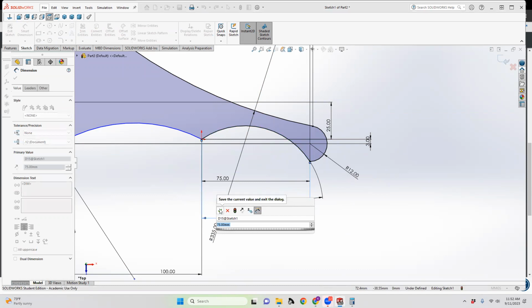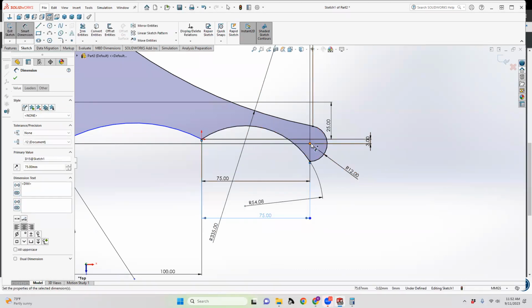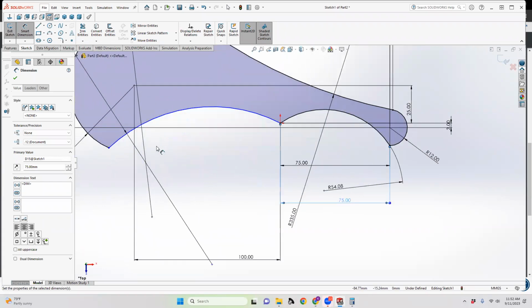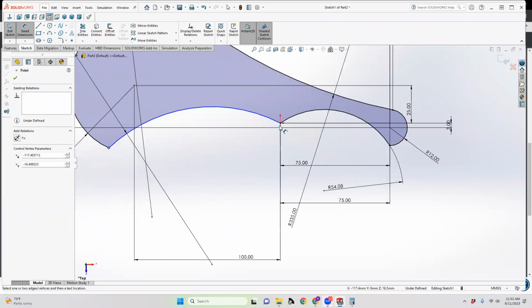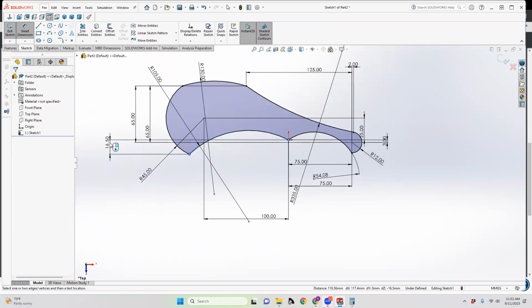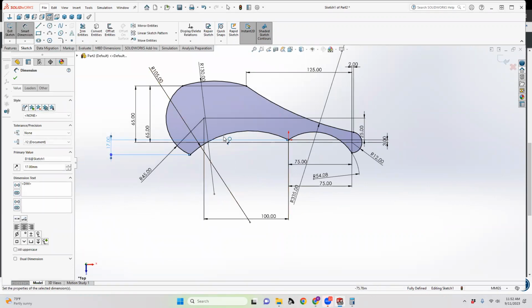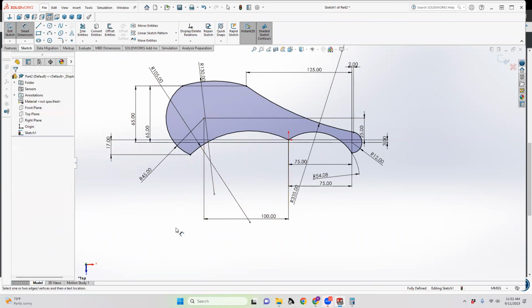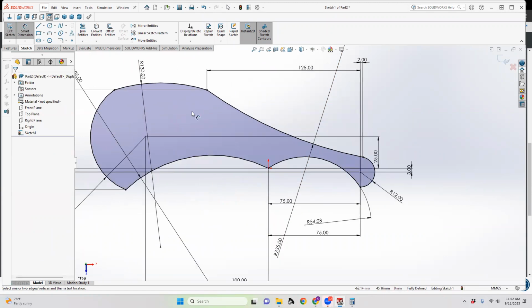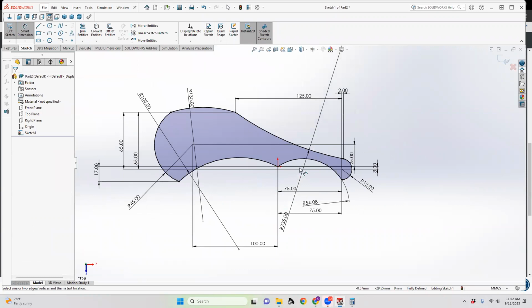That's not really helpful. In this case, because we hadn't defined the distance between this point and this point is 0, a lot of times that's going to overdefine your sketch. So in that specific instance, it didn't. But generally, if you have references in one axis, you need to grab a reference in the other axis. So something like 17. And now we've got everything fully defined, right? So you can make a pretty wild shape out of just arc segments and fully define it by telling it where the endpoints are and all of those